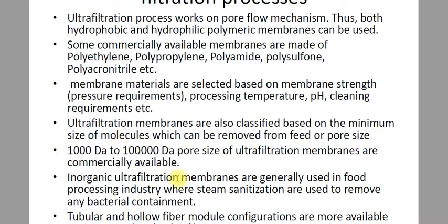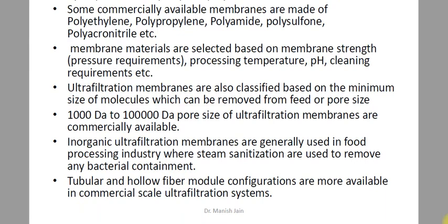Now inorganic ultrafiltration membranes are generally used in the food processing industry. Why are inorganic membranes very useful for the food processing industry? Because, suppose you are using the ultrafiltration membrane for concentration of whey protein, then you have to sanitize the membrane. Steam sanitization is very much required. Why? Otherwise bacteria will start to grow inside the membrane, because you are using it for food processing.